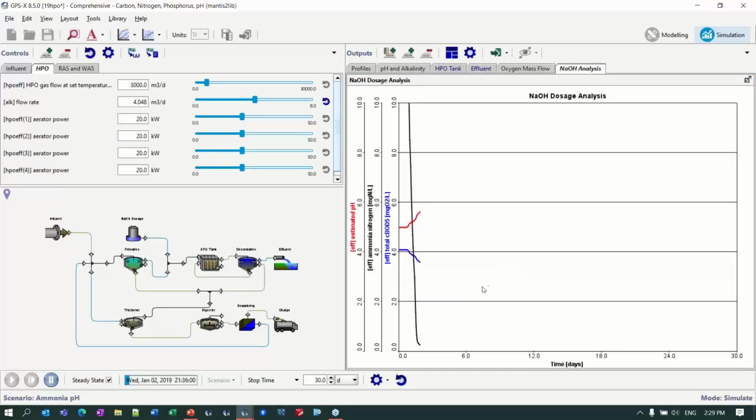I actually made a little graph here. This is kind of looking at how that changed over time. You can see our pH is coming up, and you can see our BOD is actually improving a little bit too. But here's the previously not nitrifying, which came all the way down here to fully nitrifying. So that tells us that we can take advantage of that as a way to analyze what's happening with this model.